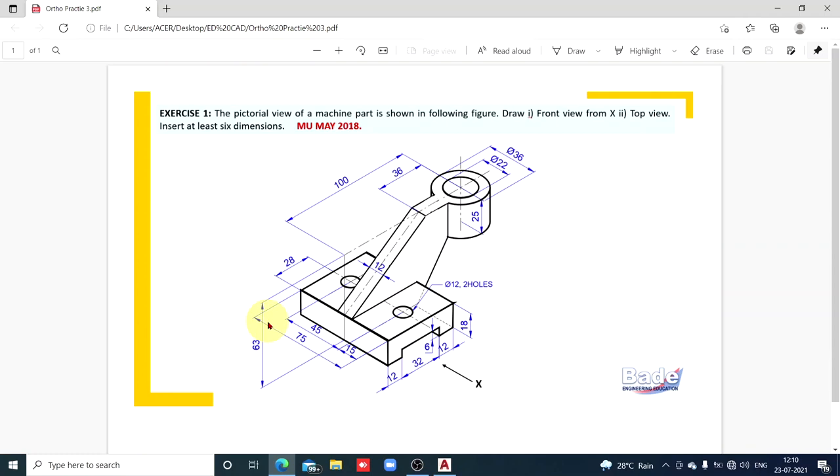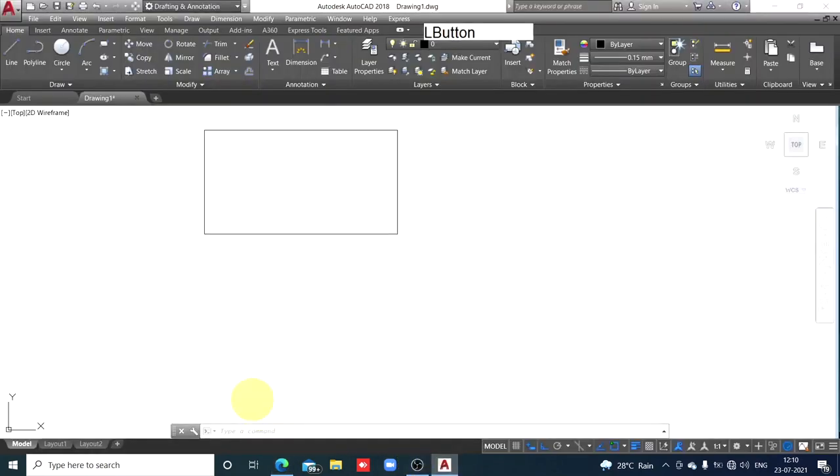In the top view, it is the length and width of the object, which is 118 millimeters and width 75 millimeters. Click on the line. Let's trace the left end downwards, but there must first be a 20 millimeter gap. So keep the cursor at the left end for some time and then track it. Leave 20 millimeter space, enter.